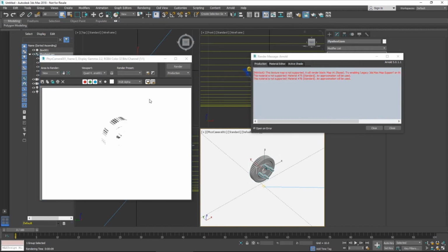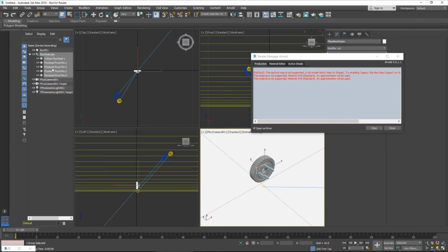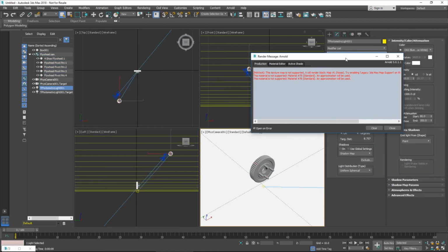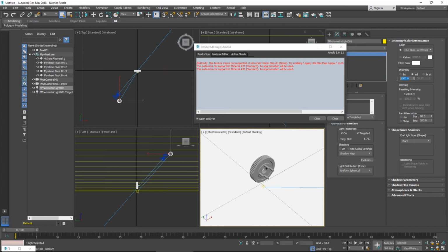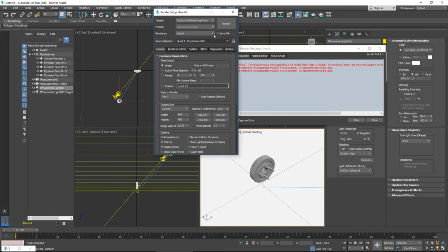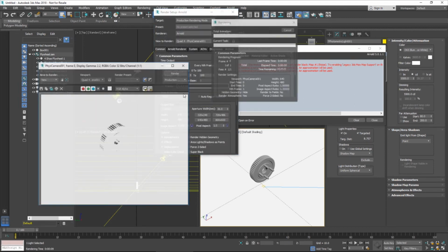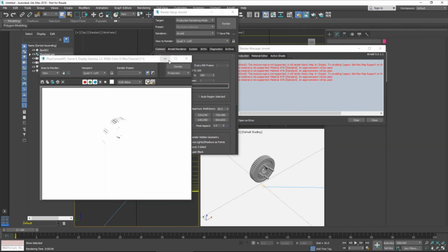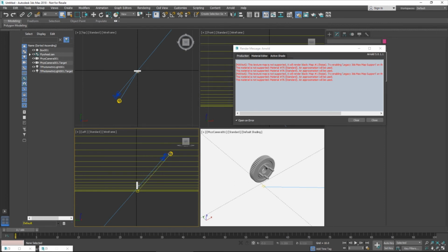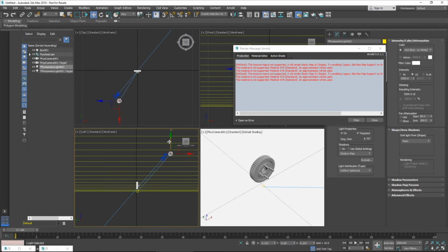Like Daniel mentioned, he didn't really mess with the lighting too much or the intensity. So we're just giving an example of what things actually look like if you don't mess with anything, like distances and lumen amounts and things like that. And so Daniel just changed the candela amount to 5500, Daniel, right? Yeah. What things like that allow you to do is change the intensity of the light, to change the amount of light that's hitting your particular object.